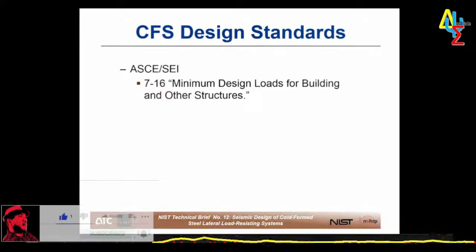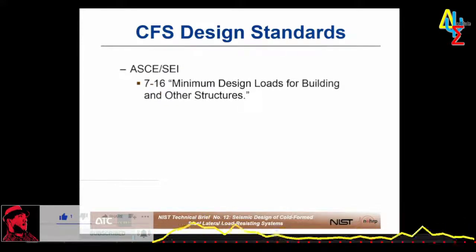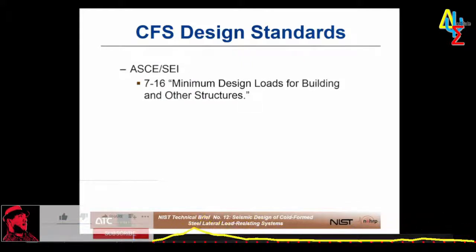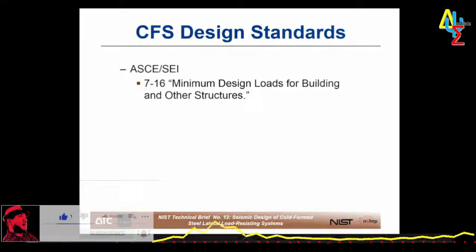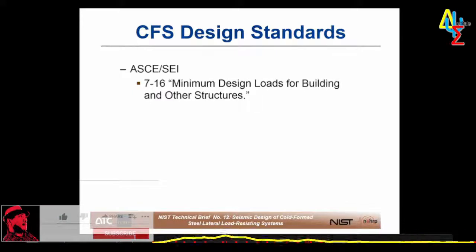And of course, no list of structural design standards can be complete without talking about ASCE 7. ASCE 7, of course, includes provisions for a variety of building materials and systems, where engineers look to ASCE 7 for seismic requirements such as the response modification factor R, the overstrength factor omega naught, the deflection amplification factor Cd, as well as specific detailing requirements for a variety of structural systems.